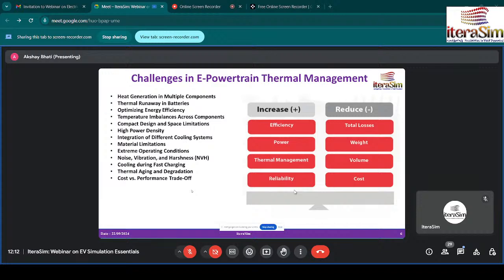That happens because overcharging or over-discharging leads to internal short circuit failure. External damage may be an issue, but the chance of external damage is very low. An internal short circuit may happen because of the product design. And high temperature exposure accelerates the breakdown, meaning if the battery is exposed to a very high temperature environment, components like motors and electronics are generating heat at a very high scale. So this may also cause failure of the battery.